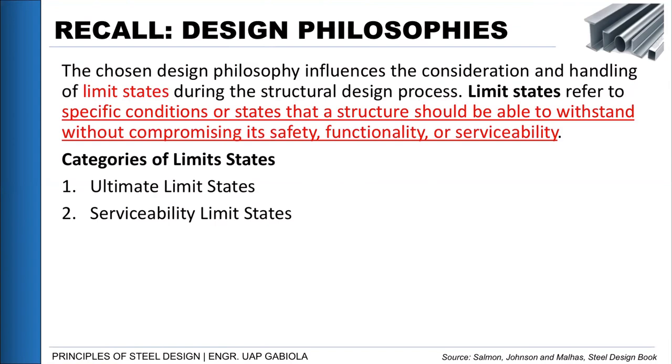And under ultimate limit state is what we call yung strength limit state, wherein strength limit state is more specific in nature. So since our subject deals with the components of our structure, magiging limit state natin under ultimate limit state will be strength limit state kasi we will be focusing on the design or analysis of each structural component, and then we will determine what specific limit state or strength limit state is applicable for each of this component.